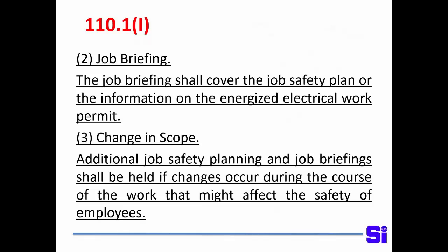According to the OSHA report, it created a fireball that was 26 feet in diameter. So there was a tremendous explosion. The technician in the cubicle was killed immediately, and then my friend died 3 days later. The supervisor died 5 days later. So you had 3 fatalities from this. And one of the things that OSHA wrote as a citation was that when the job changed, they didn't stand down and reevaluate the job.